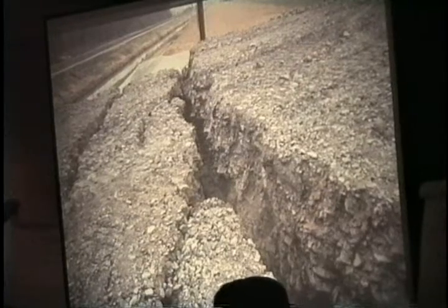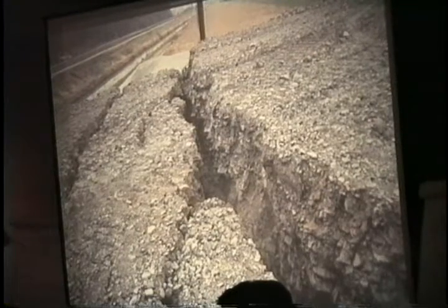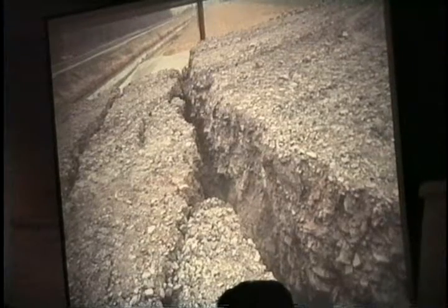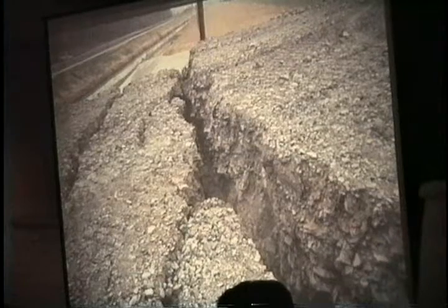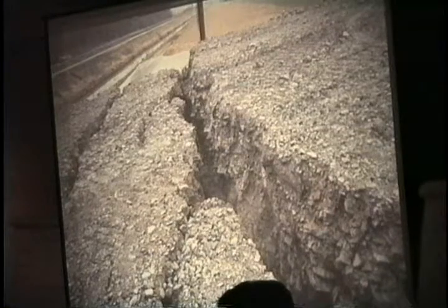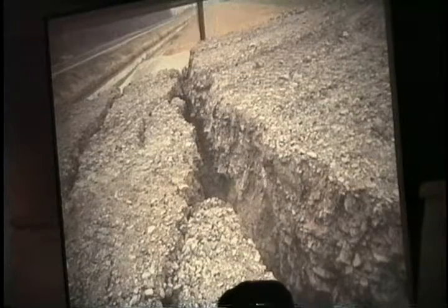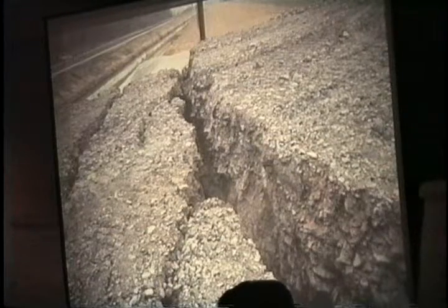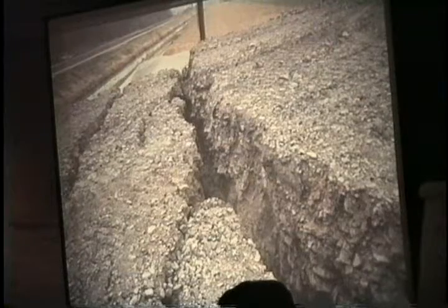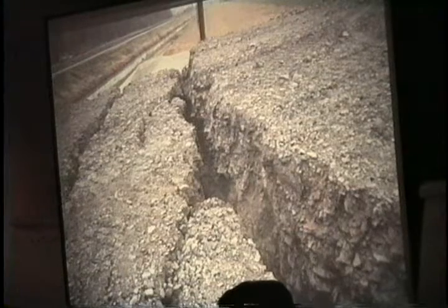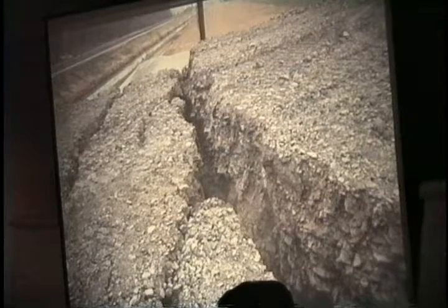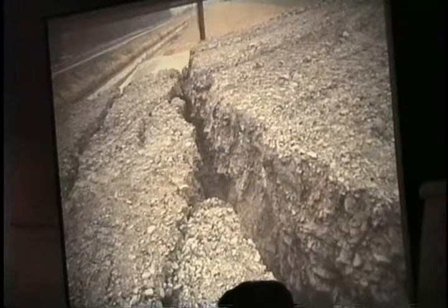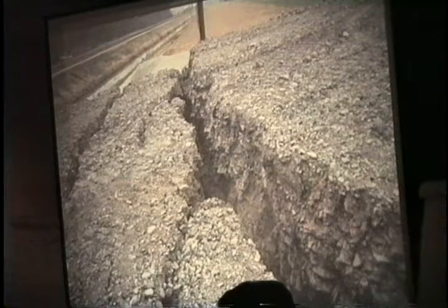The end of the story was the wall moved 10 feet. The cost of retrofit and redesign turned out to be $1.5 million. And guess what? When they took the soil samples for the clay originally, the engineers saw we had strong clay, medium clay, weak, very weak, but it was only a thin layer, and then weak, strong, strong. And in his design, he took the average shear strength.